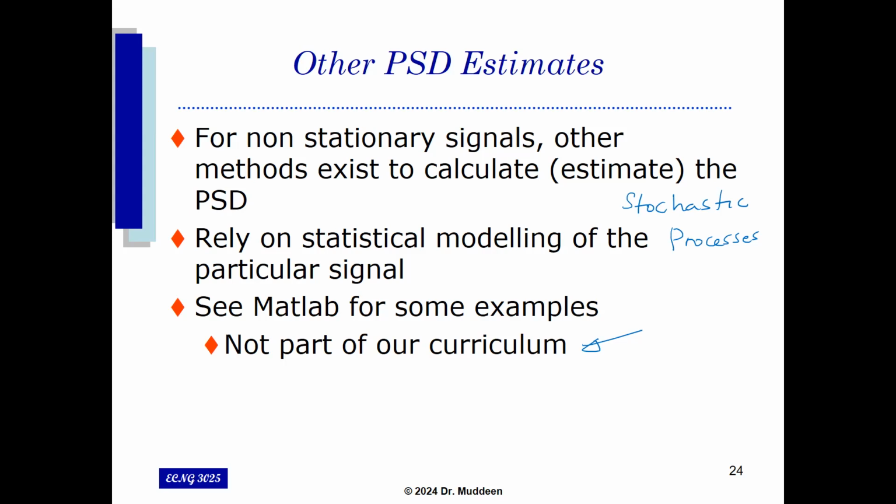You can determine that using the FFT by squaring the amplitudes of the bin values, summing, and averaging over the number of bins that you have. You can do that automatically using a particular command in MATLAB called the periodogram.